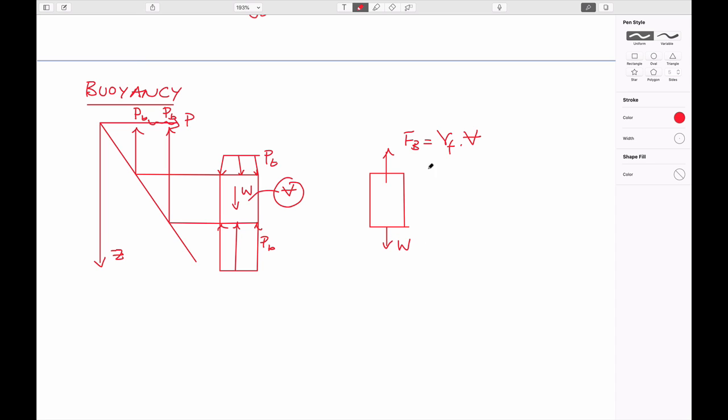And so by balancing forces, these have to equal 0. And so if we know the density and the specific weight or the unit weight of the fluid which is displaced, then we can calculate a buoyant force and apply that into our calculations for the stability, if you like, of the structure. And that, I think, is it.